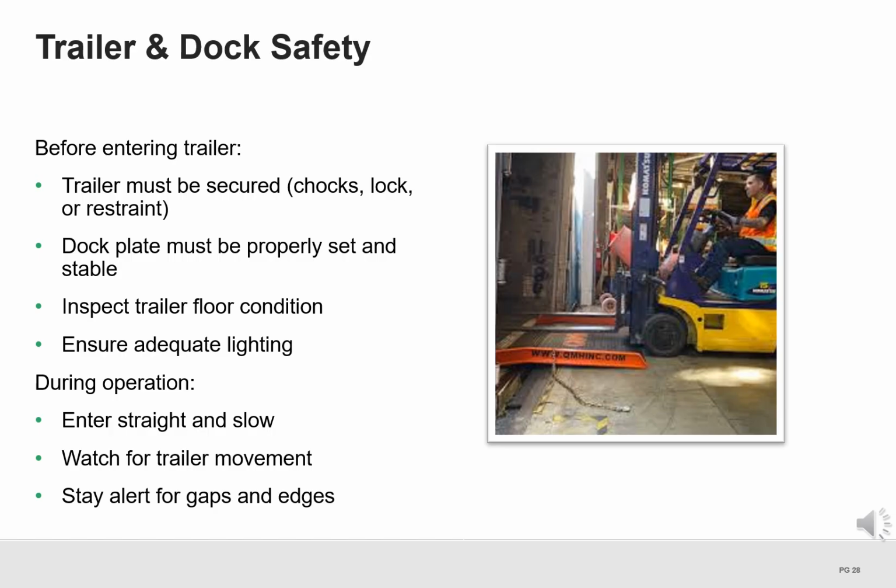During operation, enter the trailer straight and at a slow speed. Watch for any trailer movement and stay alert for gaps, edges, or uneven surfaces. If conditions are not safe, do not enter the trailer.